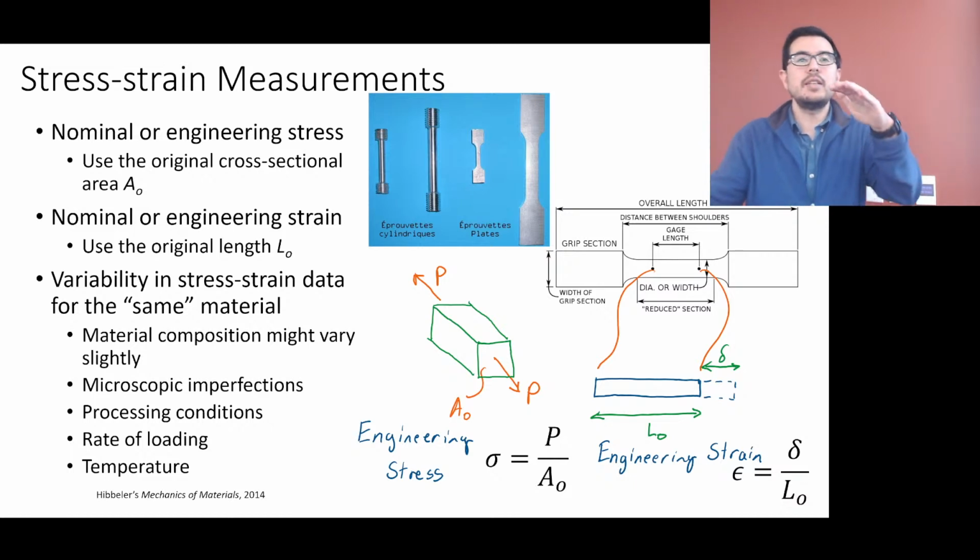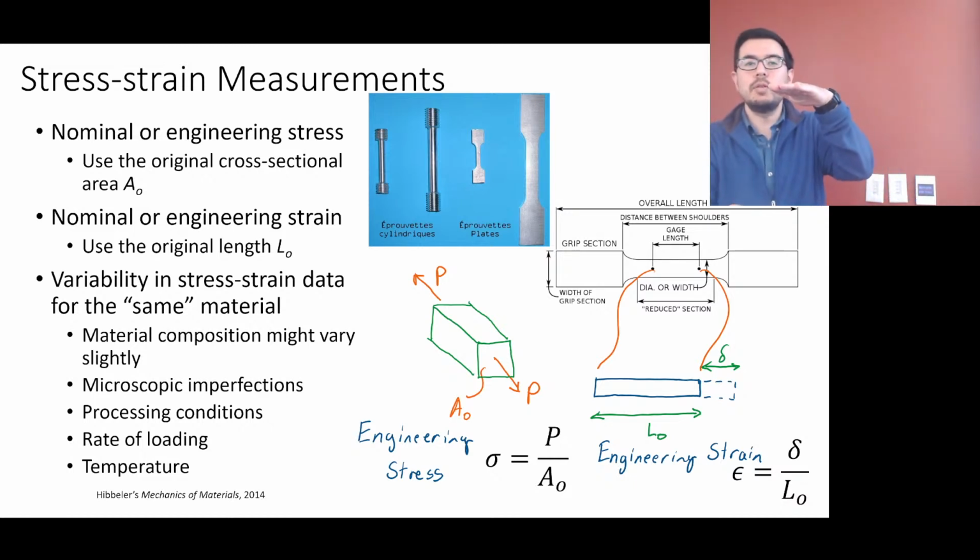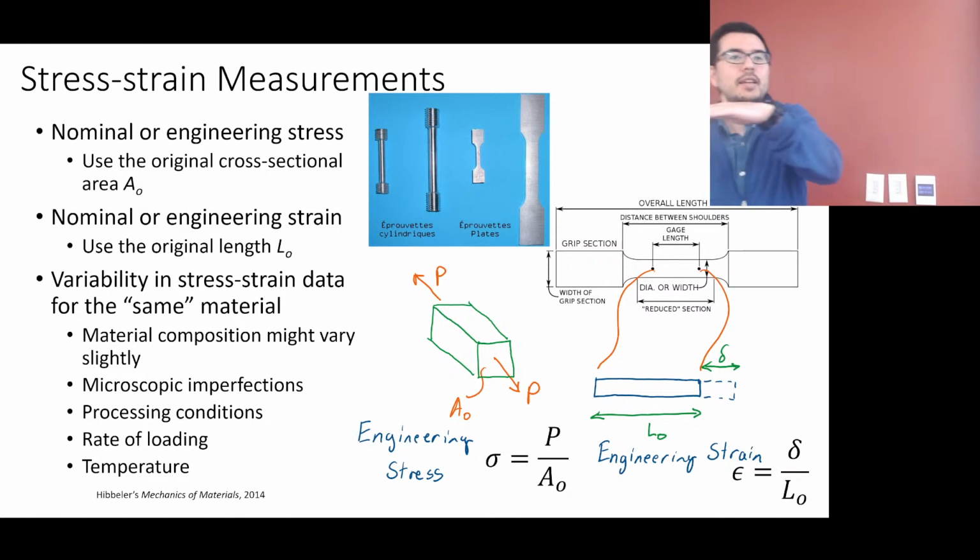Well, let's just imagine that both the 100 newton load cell and the 5 kilonewton cell have a range between 0 and 10 volts for their output. Okay? So that means that the 100 newton load cell, right, you're going to have 10 newtons per volt. Whereas the 5 kilonewton load cell, that's 5,000 newtons over 10 volts, or 500 newtons per volt.